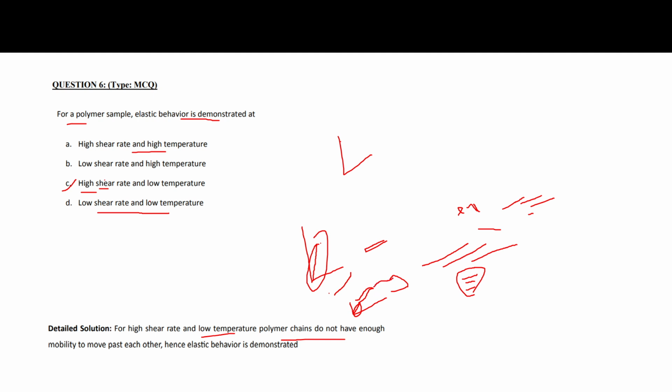But when the polymer has viscous deformation, there will be permanent changes in the polymer sample. It will never come back to its original position when the polymer has some viscous property. The polymers we generally use are semi-crystalline polymers, so they have that viscous property. If you stress it beyond a certain load, it will not come back to its original position. That suggests viscous deformation.